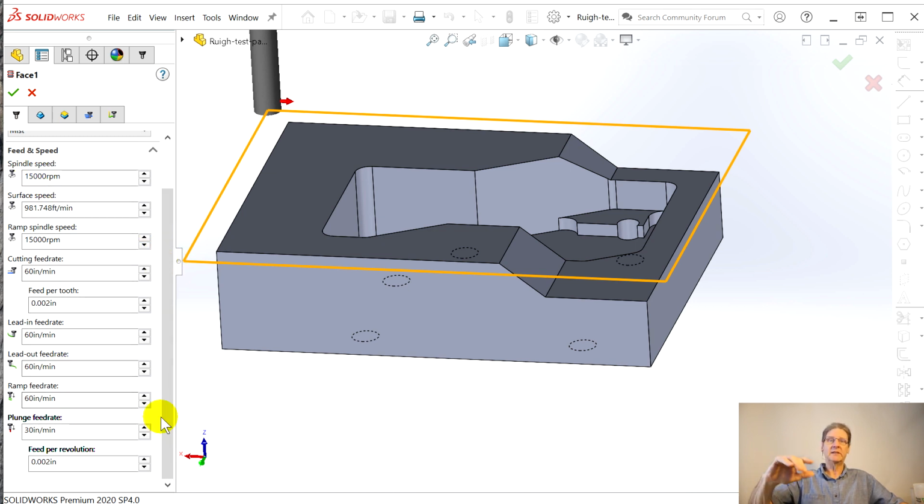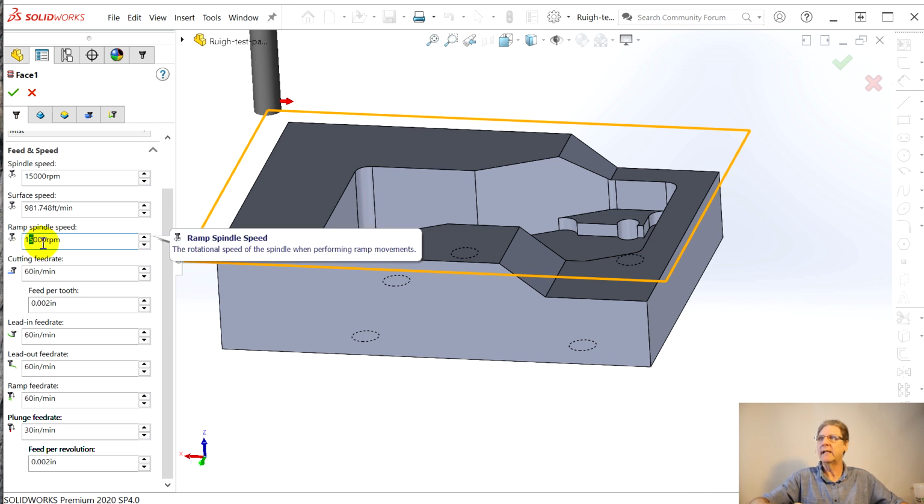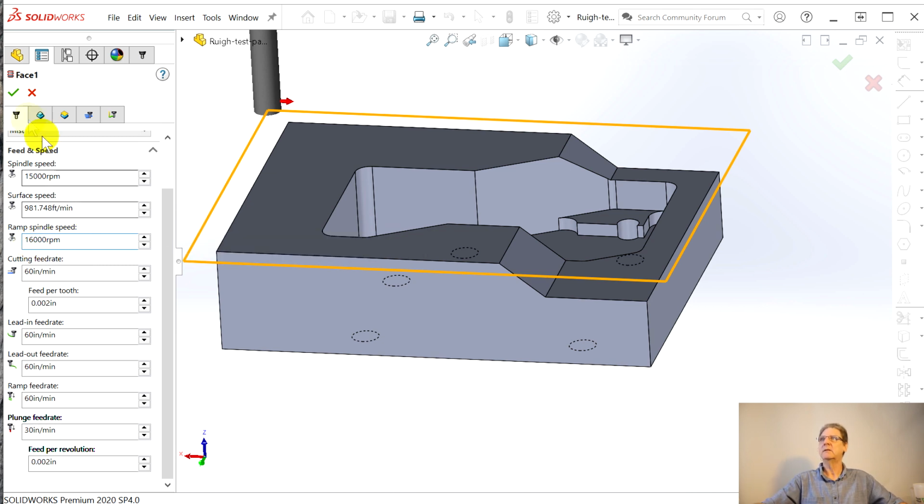Here's the speeds and feeds that I put in that tool, right? There's tabs for feeds, that feed and speed tab where the number of flutes is. That's where I set all this, and it's brought that in, but you're allowed to change it now for this particular operation from the default. I'm not sure that changed. Let's try that. Okay, so 15,000, which belongs to the tool, that's data inside the tool, let's change to 60. Okay, so we got that. Let's change focus, stayed 16,000.